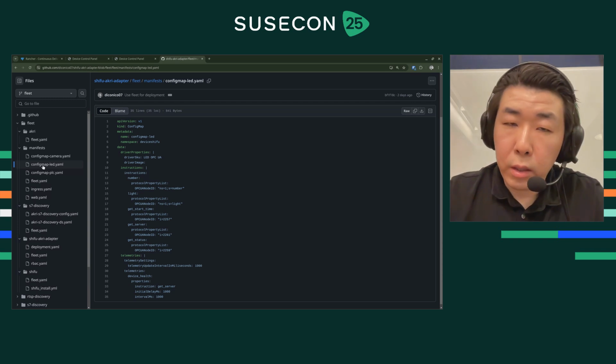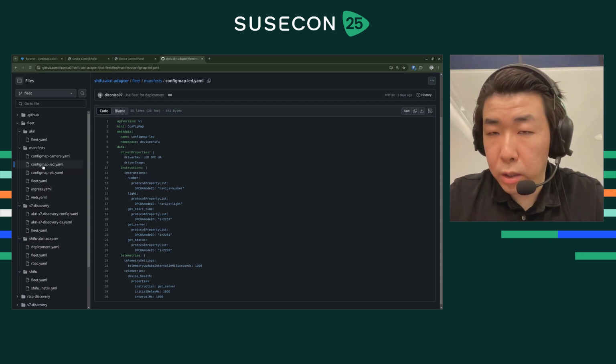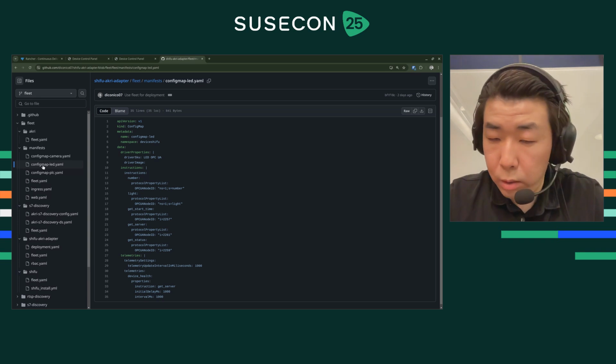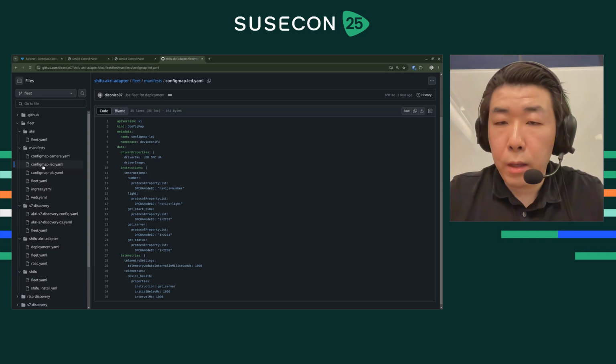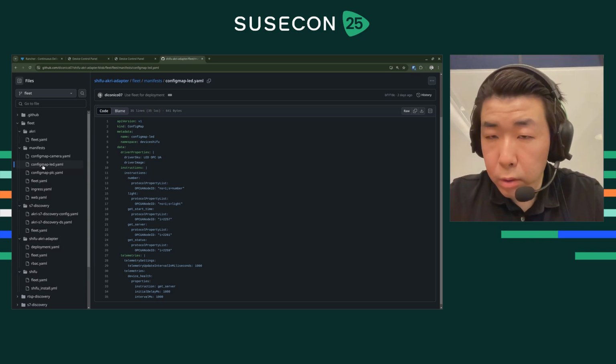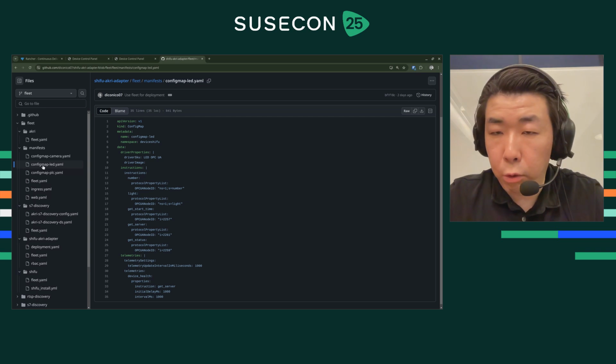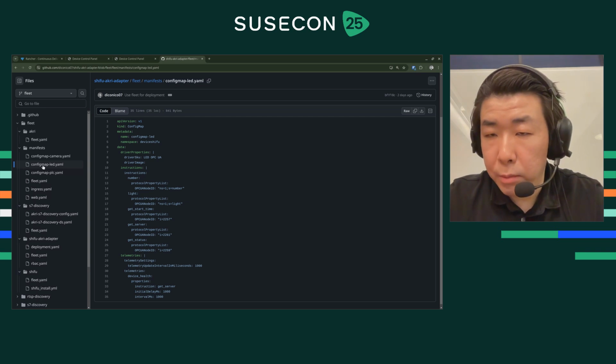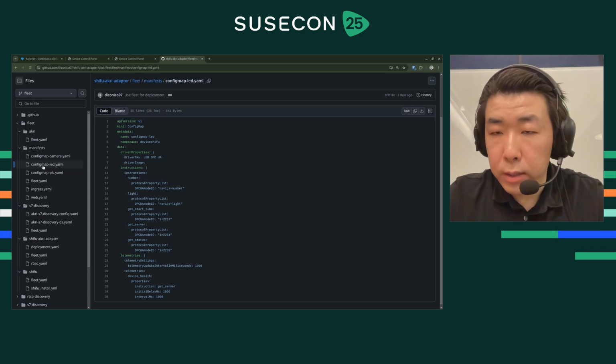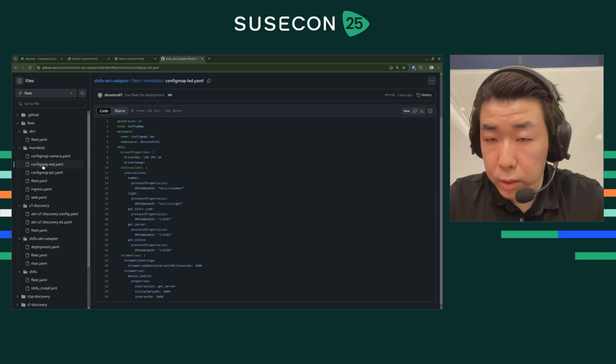And when I send an HTTP GET request, or PUT request for write, for example for number, it will translate to OPC UA node ID namespace 1 and s equals number. That part is the protocol translation.